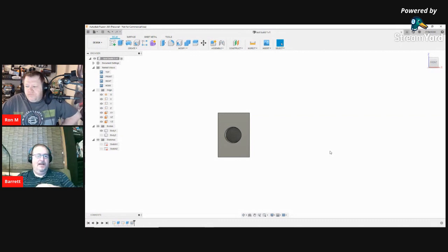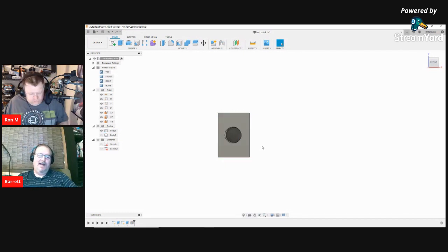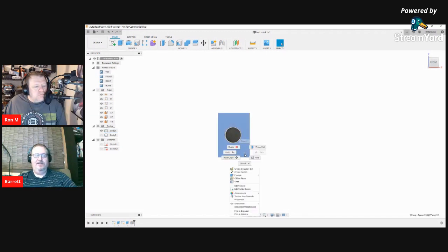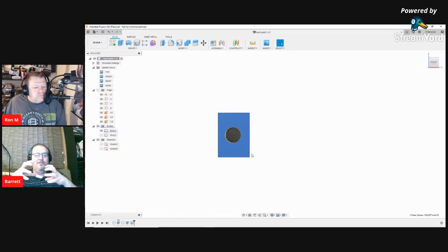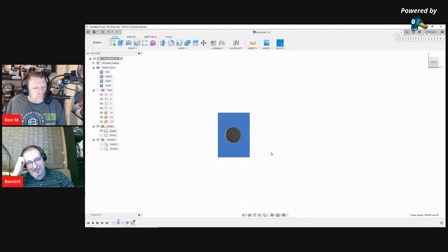You can force it to do a manual save, but it auto-saves after most of your changes. Now, you asked me at one point about editing STLs and bringing in another STL. One of the reasons that becomes very problematic is that nice little history feature that we've been using down the bottom. In order to use the function to import the STLs, which you have to import as surfaces, you have to turn off the design history in that document, and it basically means you've got no undo, no redo.